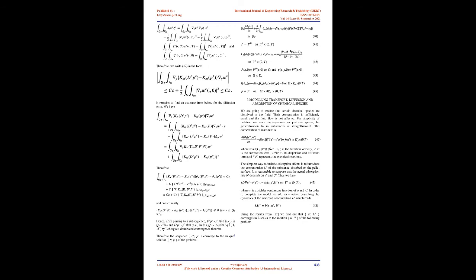After scaling the equations with the characteristic time Tc equal to 2×10^4, we take the time step 10^-3. This numerical approach was developed in 2D turbulence simulation by Robert and Rosier [22], and the method is very robust for the nonlinear coupled transport and diffusion.